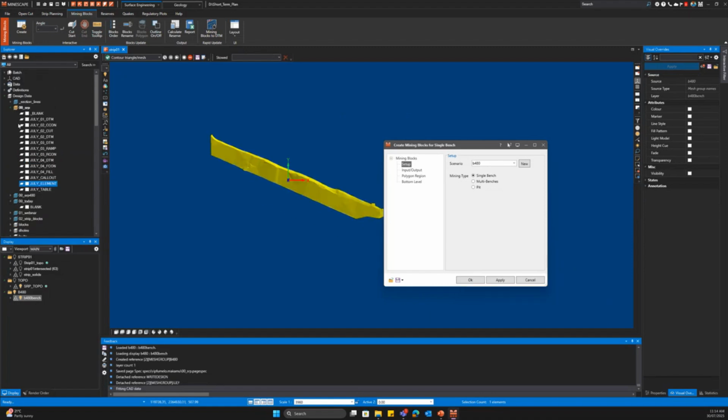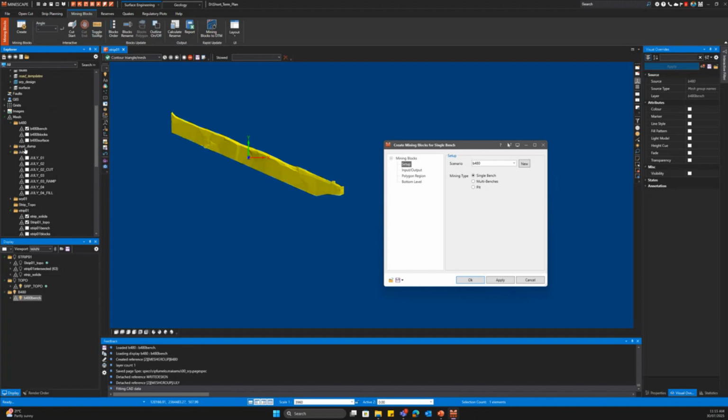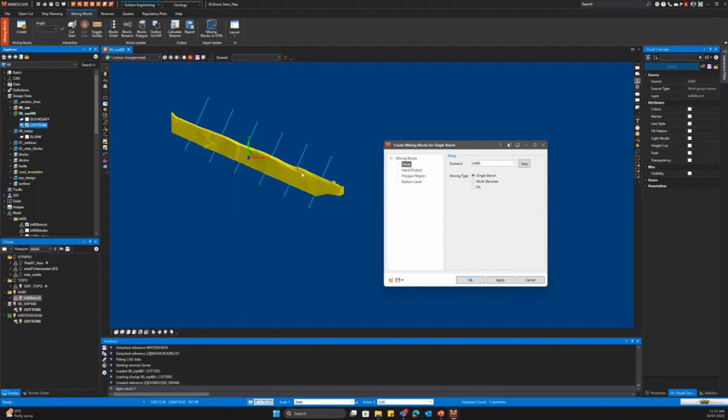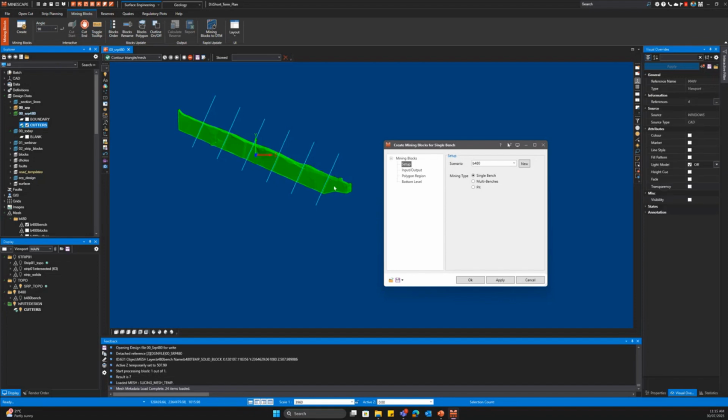And what you can do with this block, you can actually go ahead and slice it into small mining block units that you want to have. So you can go and create those small mining blocks. So I can say, I want to have different cutters. For example, I want to cut it using these cutting lines. And to do that, you can define your cut angle. I'll say 90 degrees and say cut start. I'll select this one that I wish to cut. So it will automatically cut it for you, as you can see.